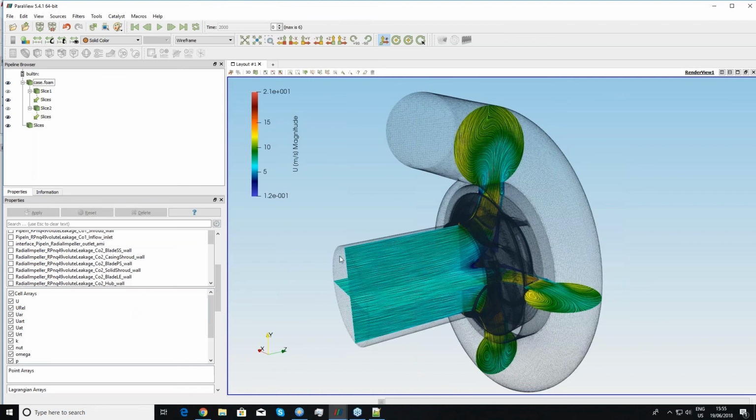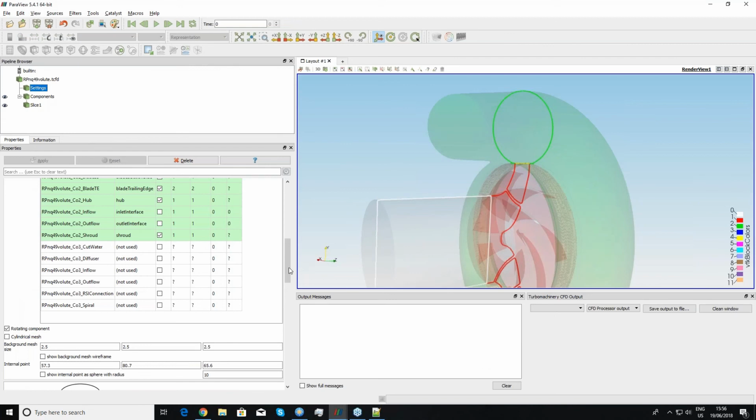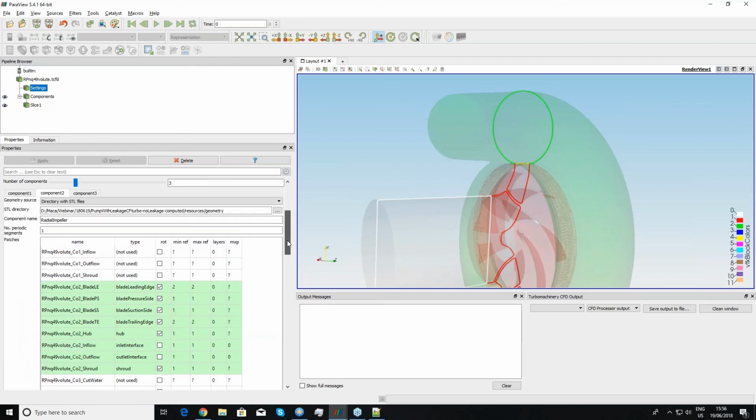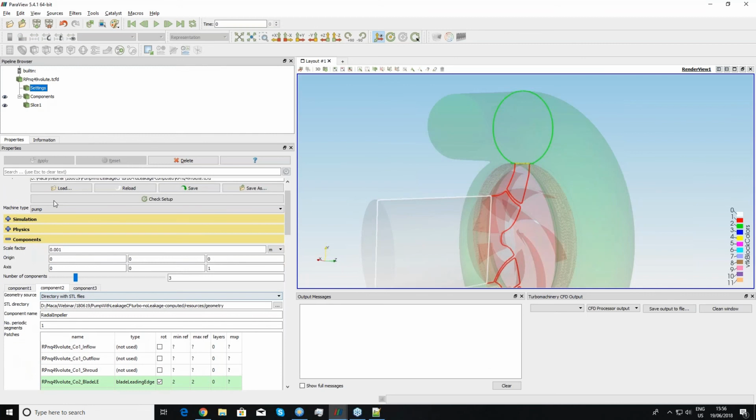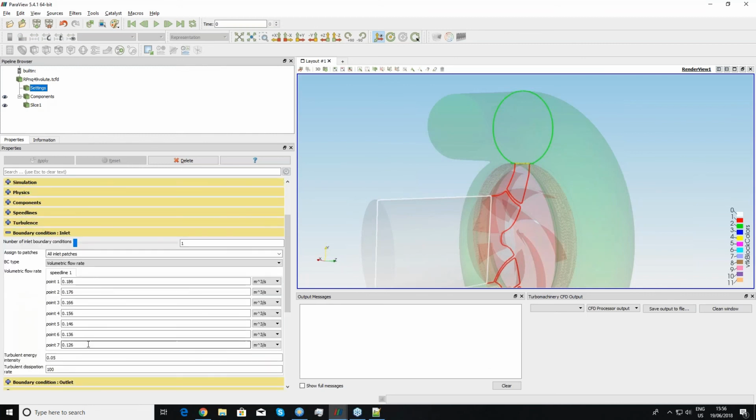Yeah. So if you set here, I hope you still see my screen, right? So in the setting of the boundary condition, here basically if you go up to not 0, with the 0 it doesn't work, but if you really set maybe something like this, or even less maybe, but not 0, it will work and it will simulate the shutoff condition for the pump. Yeah, so basically it is possible.